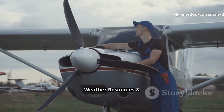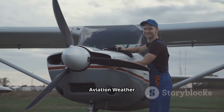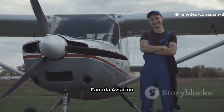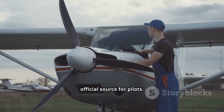3. Weather resources and pre-flight planning. You are responsible for checking weather conditions before every flight. 1. Aviation weather websites. Use sources designed for aviation, not just a standard weather app. Environment Canada Aviation Weather provides METARs and TAFs. NAV CANADA Aviation Weather website, the official source for pilots.